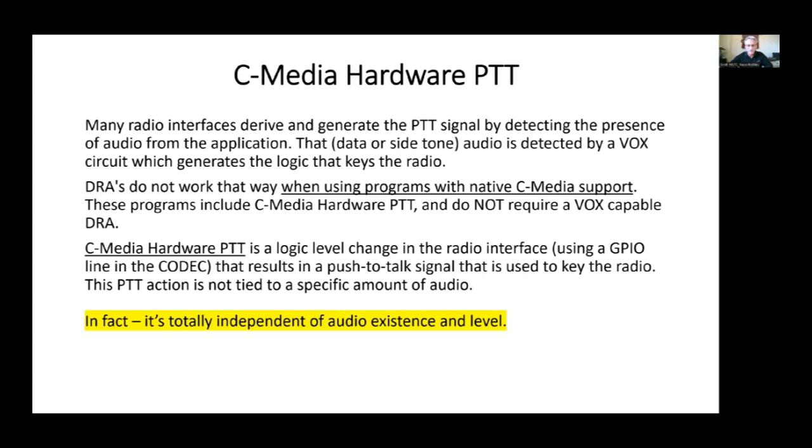That presents itself to the operating system as a human interface device, or an HID, which is like a mouse or a keyboard. And those things are inherently shared devices. So when you've got a COM port generating your PTT, only one application can use that at a time. Whereas an HID interface that we're using here in the C-Media device is a shared thing, and it can be utilized by multiple applications at the same time. So I can have VARA FM up and I can have UZ7HO up both at the same time, and both sharing that hardware push to talk interface.